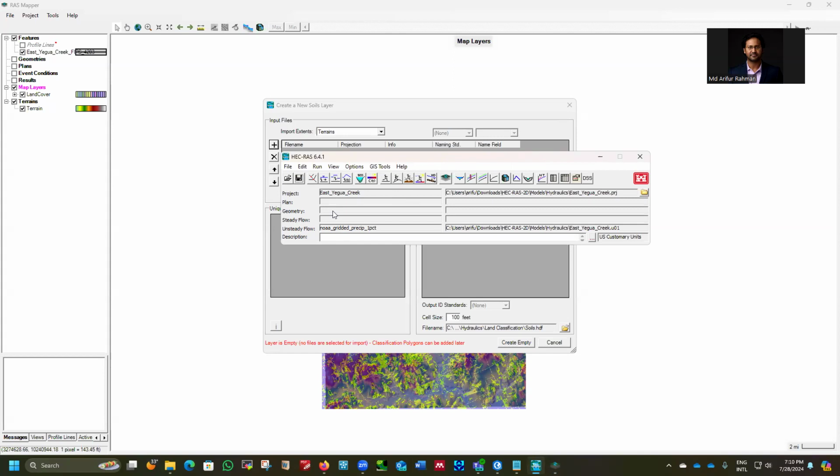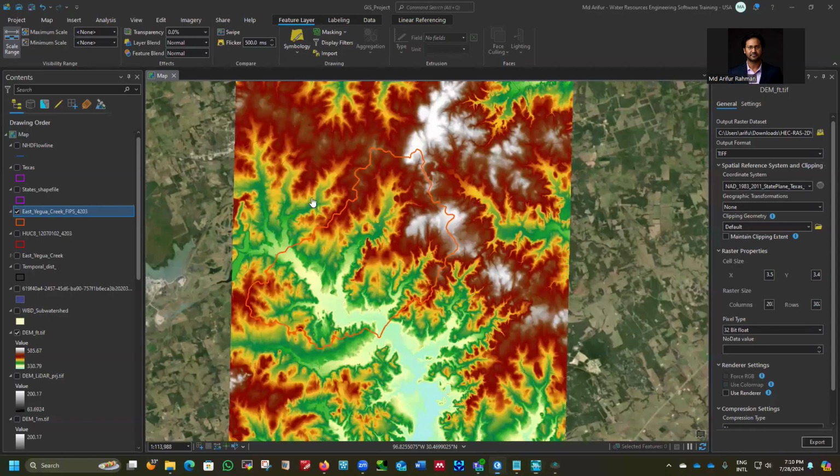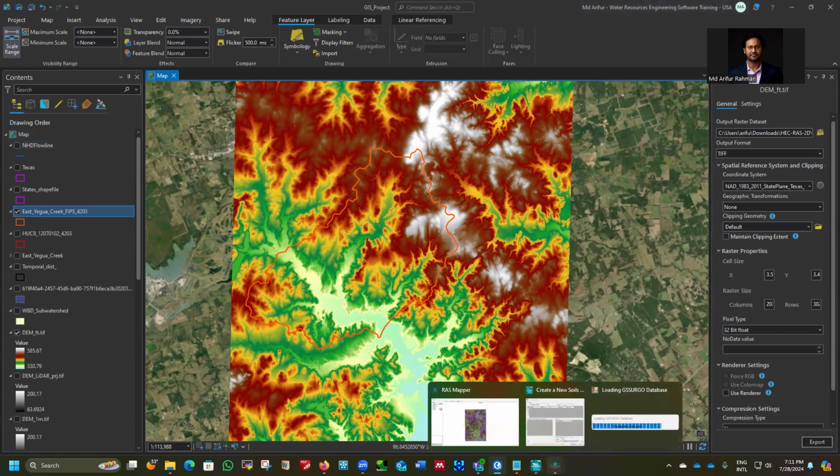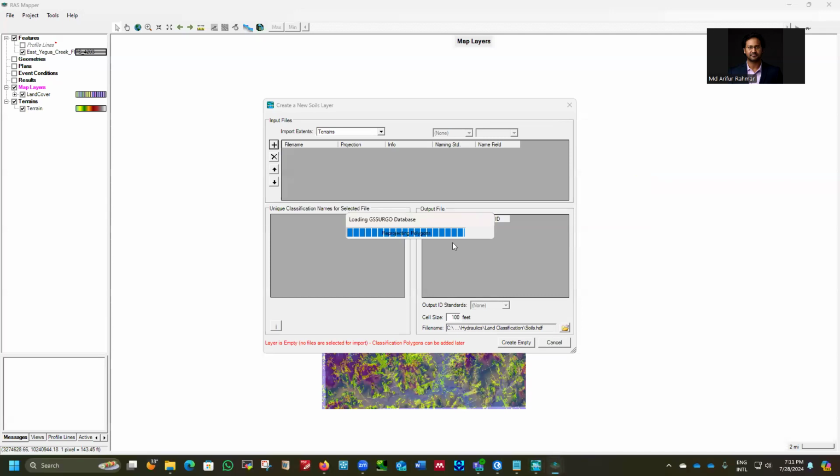We'll create the geometry file, and then from there, we'll use this boundary as a parameter to generate our two-dimensional mesh. And we'll download the roadway. We have our NHD Plus flow line. We'll use this to refine the mesh. Yeah, we'll check whenever we're done with this processing.